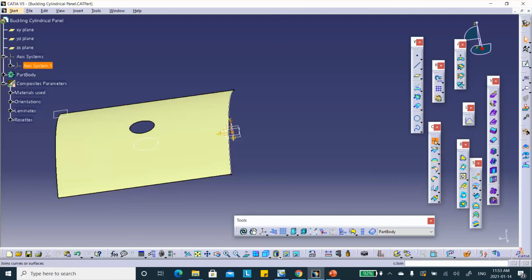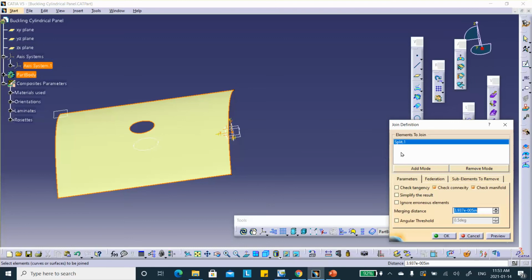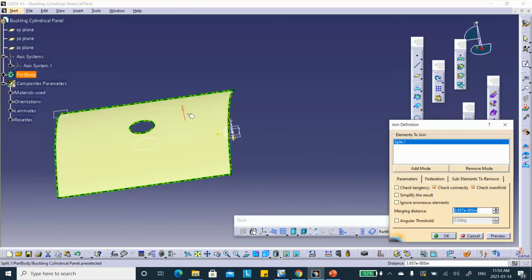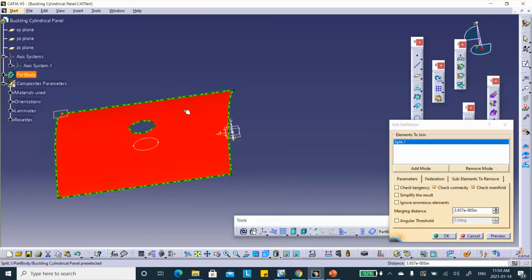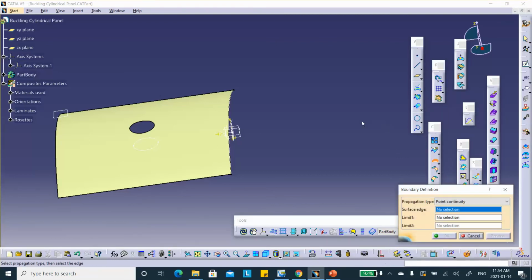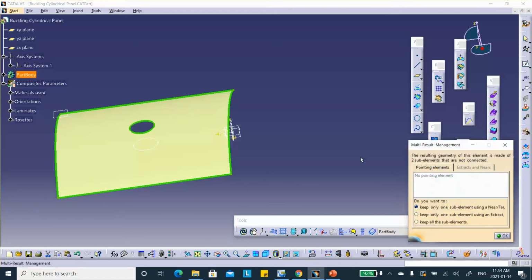So join this. Ordinarily, I like to join, and if you double click on it, it shows a draping direction. Well, that's not the draping direction. This is the direction of the surface. I'm going to flip it. Okay. Finally, I get the boundary. I could have got the boundary before, but I just did the join and then extracted it. Okay, right there. So this is going to be used as the boundary of the zone. Okay, good.